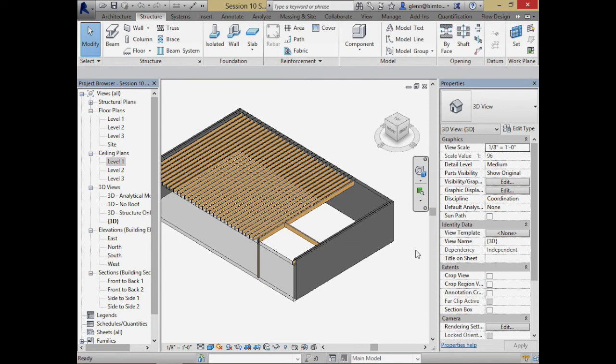Adobe and compressed earth. Very good. Now Adobe is a really big, heavy material. Are you building on top of a concrete frame, or is that going to be right down to the earth? I was going to do it right down here. I was planning on having a double Adobe wall, one that's more structural and one that's the facade, and that way you can also get the insulation. Got it. Planning on doing wood framing within the Adobe.